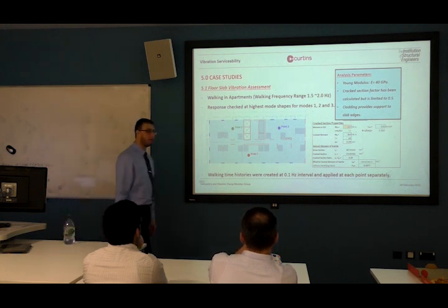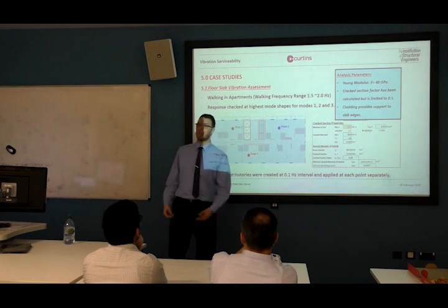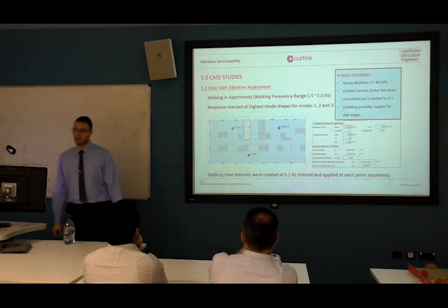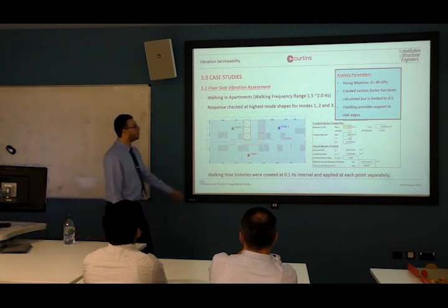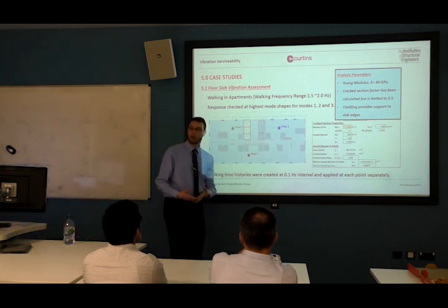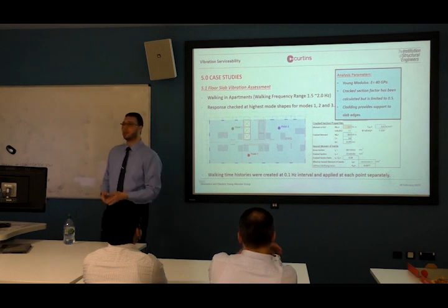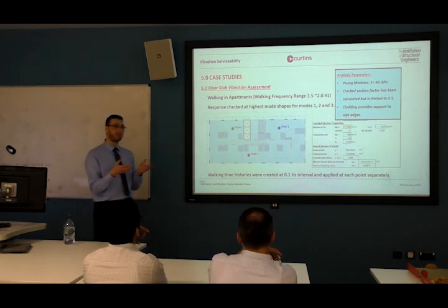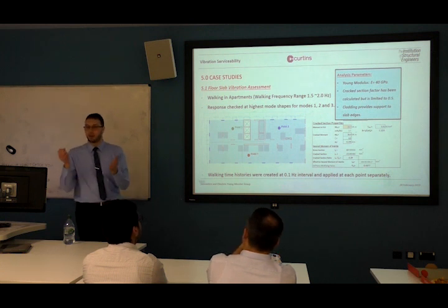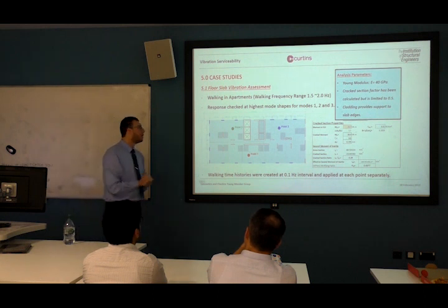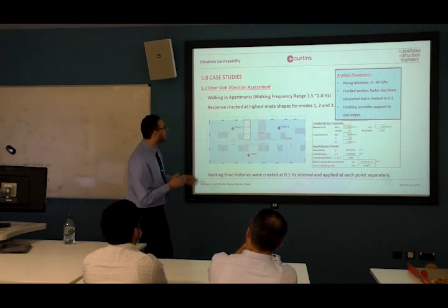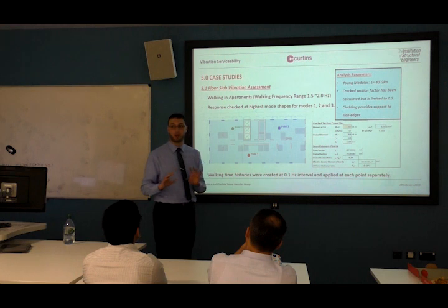So we know that concrete relaxes with time. You have some creep, you have some shrinkage. So you have to think about cracked section properties. Okay, so the moment of inertia is not the same. Usually they crack it by 0.3 or 0.35 for slabs. So what we said, we're not going to crack it for 0.3.